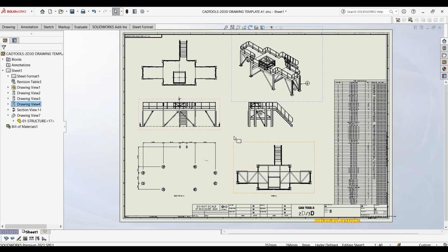Okay, now that we're here, guys, I think we're set up with the views, with knowing how to put the bubbles, how to put the dimensions, how to put the second view, and how to hide views in order to see what's underneath.